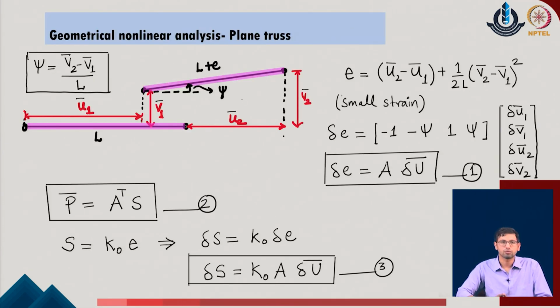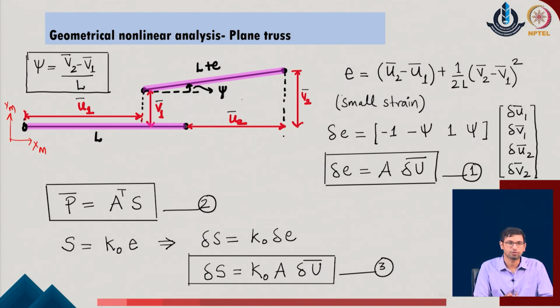So, we are doing this problem with reference to a plane truss. Initially we have considered a standard member having two translations at both the ends. We identified the given member in the generalized member coordinates. The structural coordinates could be completely different, in a different orientation, but we first identify the member coordinates and locate its complete stiffness parameters at the beginning, and once we are able to do it, we will modify the system stiffness to the generalized global coordinates.